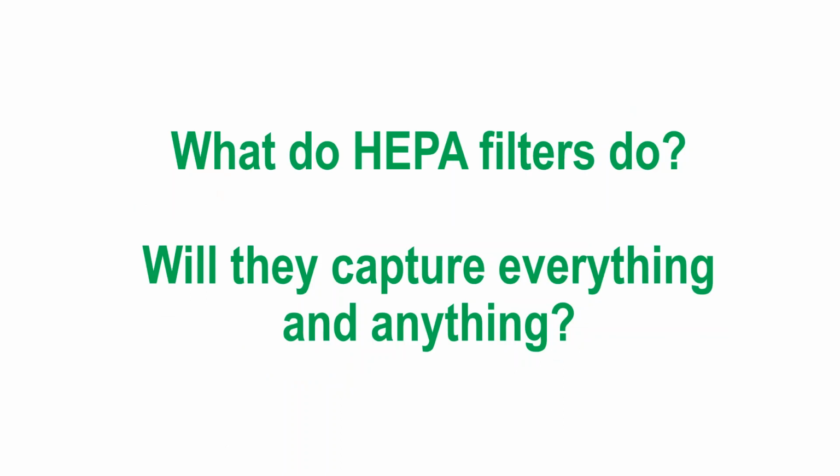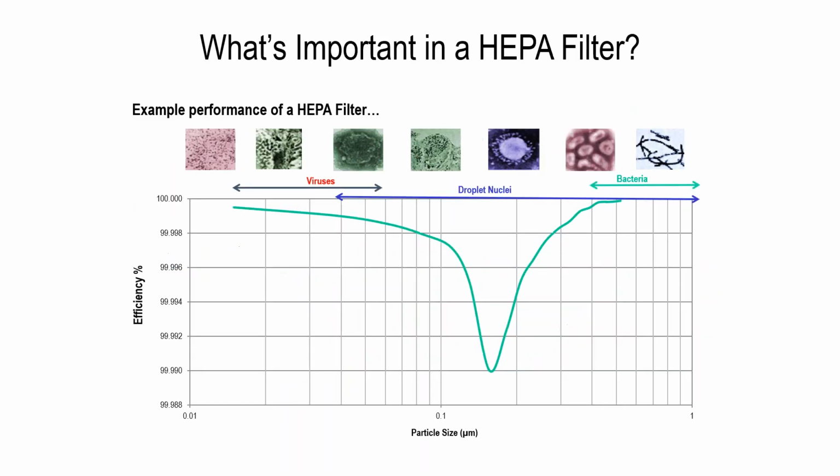So what do HEPA filters actually do? Well, they capture everything. This slide is from last year for those of you who were nice enough to join us back in January, where we did a quick Q&A on HEPA filters. Once again, just as a quick review, HEPA filters are really good at filtering gigantic particles, but that's not why we spend the money. We don't want them installed to do anything over 10 micron. We want them smaller than that, so PM10 and below. That's really where they shine.